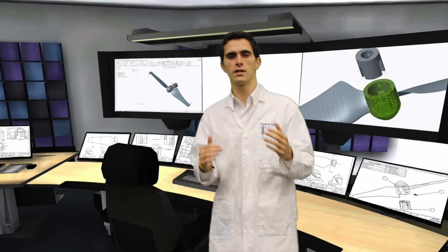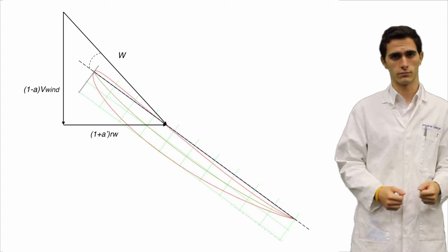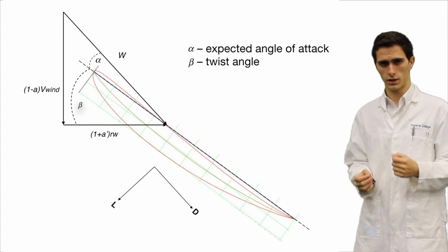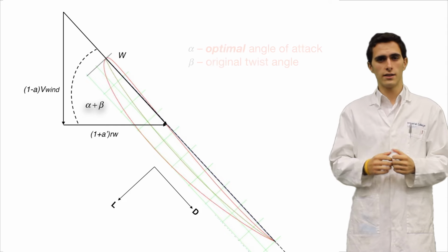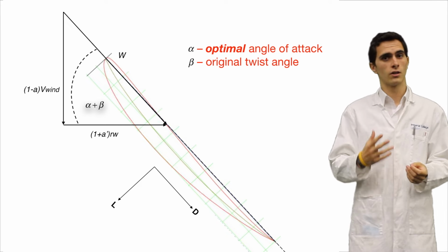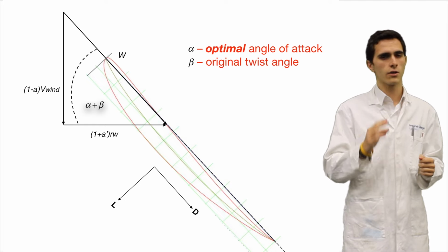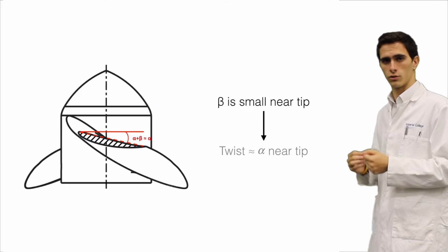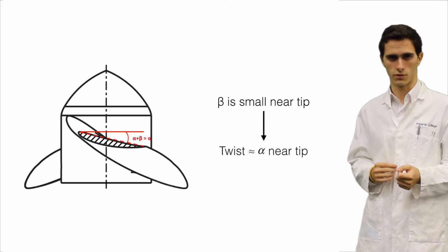This issue is thought to be mainly due to an oversight in the MATLAB script used to generate the twist angles to be inputted in the code. The inputted angle should have been beta only. Unfortunately, due to a miscommunication, the inputted angles were alpha plus beta. This led to lower angles of attack over the whole blade, and thus to the reduction in power generated, torque, and RPM. However, this additional twisting increased our chances of self-starting, since the cross-sections near the tip were originally untwisted, and thus, by simple conservation of momentum, more torque was generated at no rotational speed.